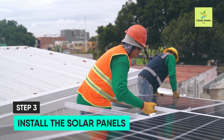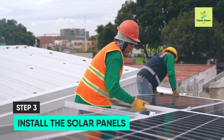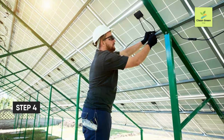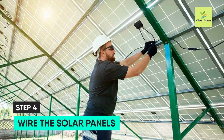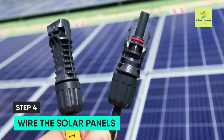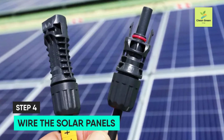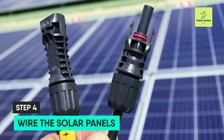The third step, install the solar panels. When the mounts are set up, the solar panel itself has to be installed on the mounting structure. Make sure to tighten up all the bolts and nuts so that it stays stable. The fourth step, wiring the solar panels. The next step in the installation process is to install the electrical wiring. In most cases, MC4 connectors are used because they are suited for all types of solar panels. Make sure to shut off the household's electricity supply during wiring installing.